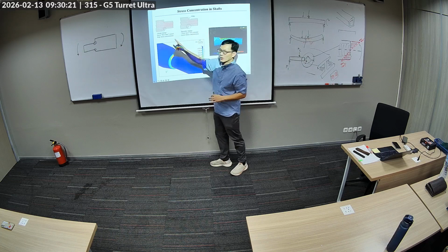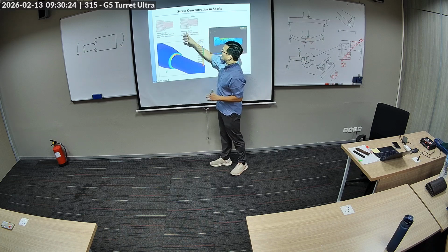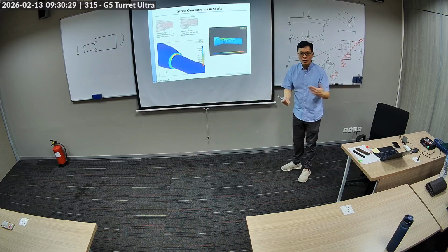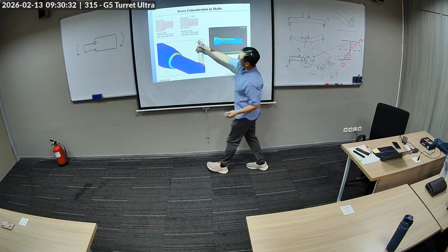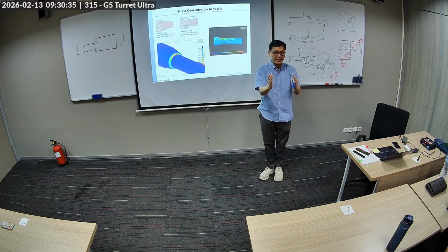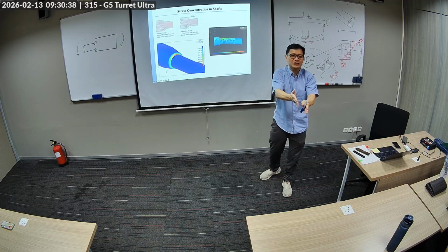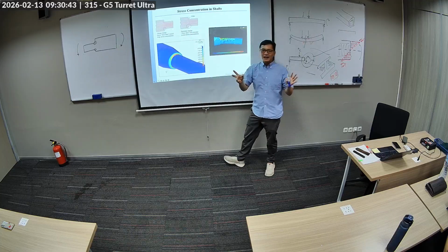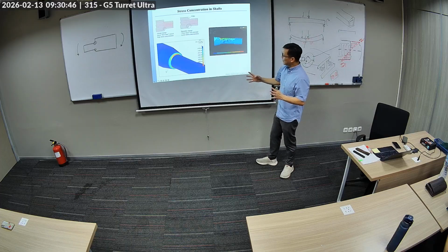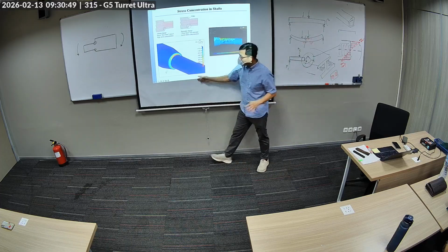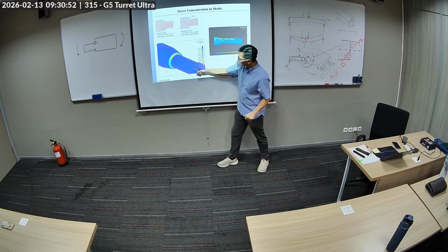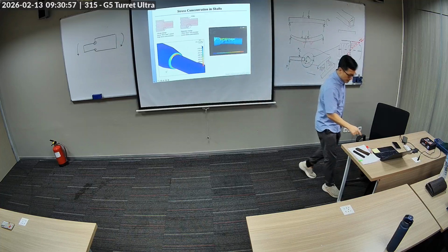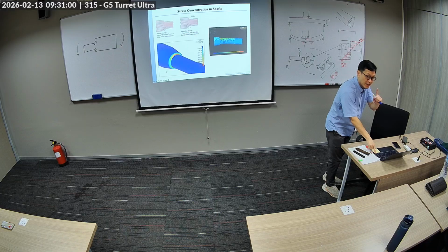This is called the stress flow lines. Okay, so these flow lines, it's actually an analogy of like a hose. If you stream water through a hose, and then there is a sudden change in diameter, the water is forced into it, right? And so these flow lines are kind of the analogy of stress concentration. So if I have a shaft like this, and I load it with bending, you see the red color, that's the maximum stresses. Okay? So that's the location of the failure point.